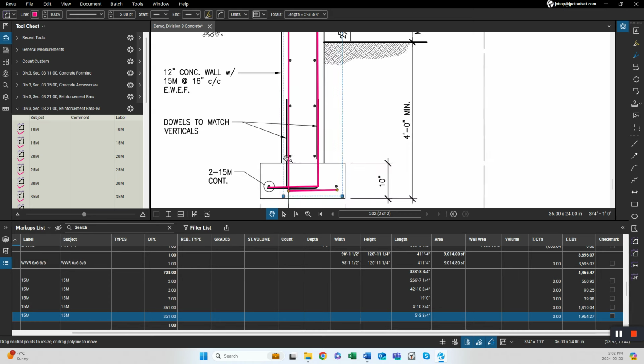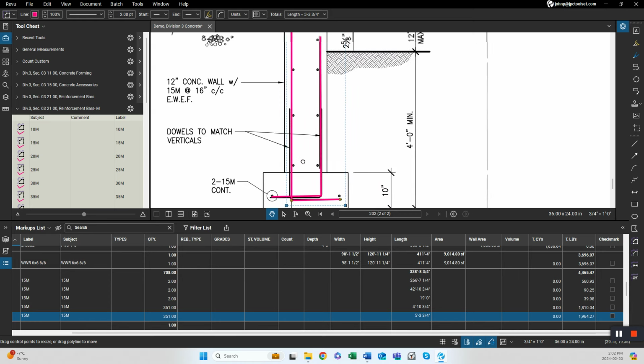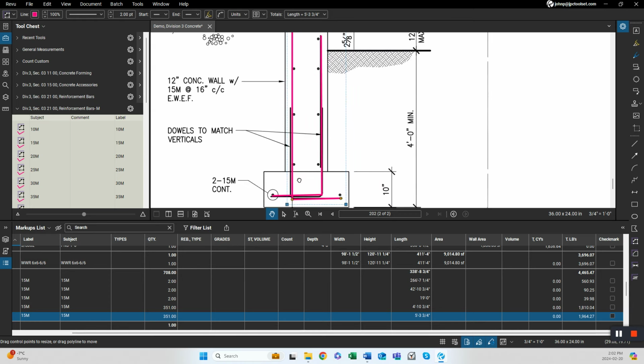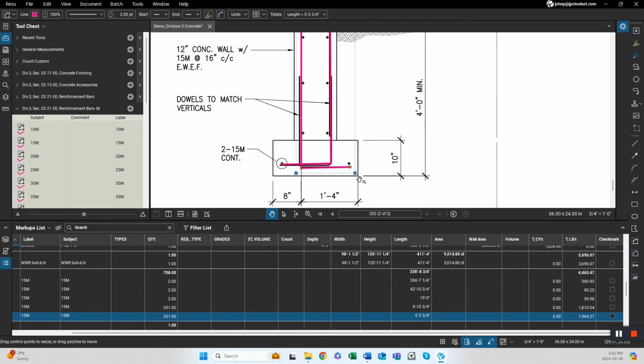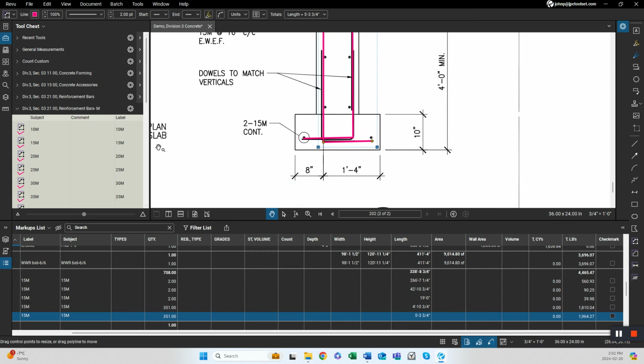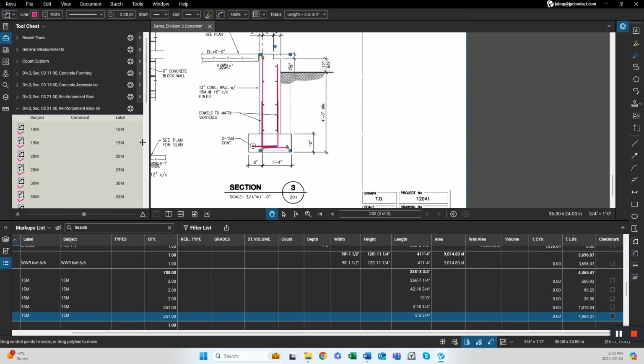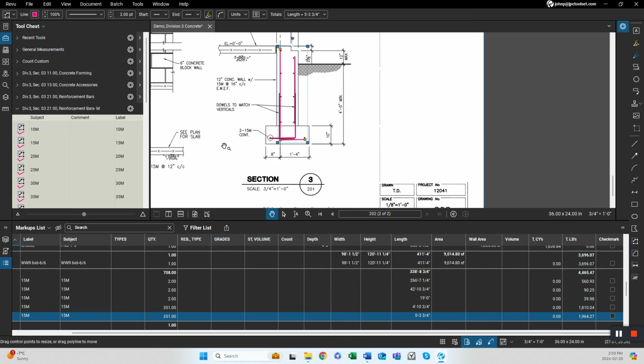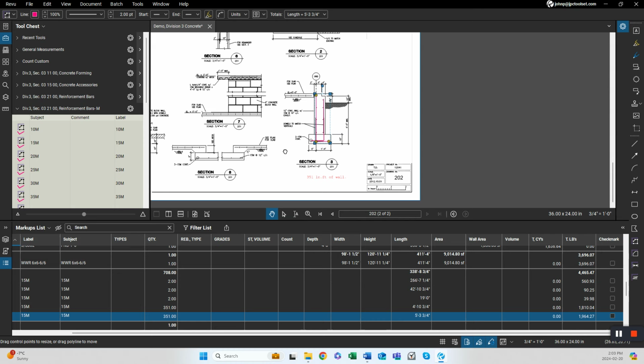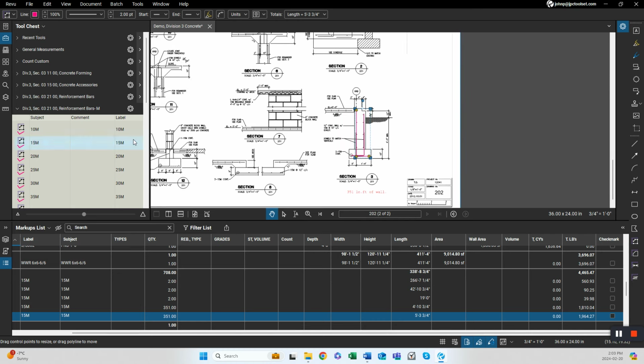And again, for my rebar and my vertical walls, I would do the same thing as what I did in the footing. I would lay out one rebar and after that change your quantity. So I hope this demo is beneficial to you guys and will assist you on creating a more accurate takeoff and more efficient way of doing it instead of doing it by hand there.